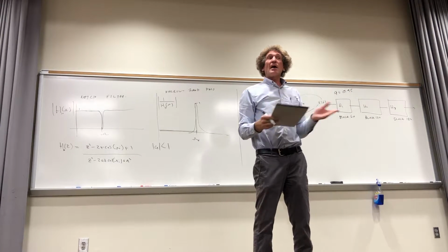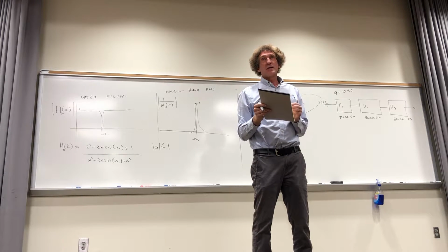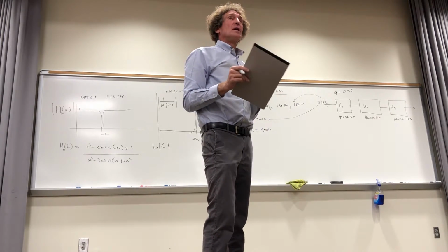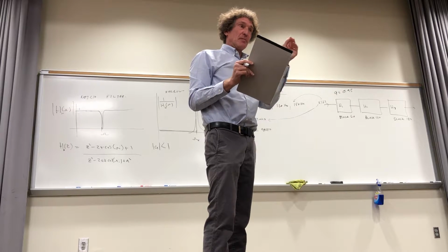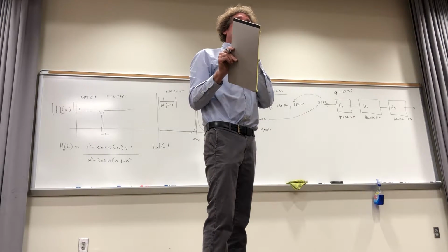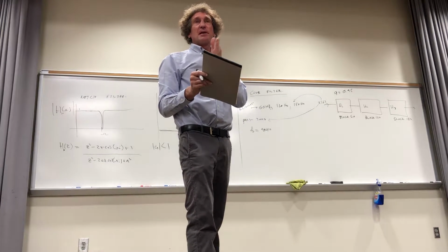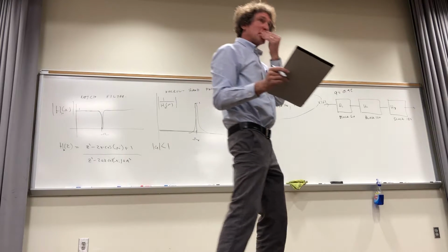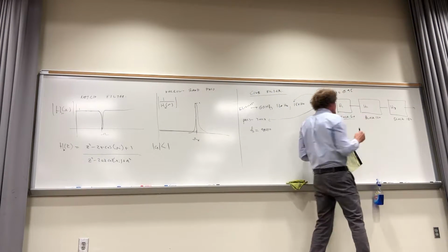Remember, the higher the value of A, the narrower the band is, right? But there are some problems because if it's too narrow and there's any jitter in the signal that you actually want to filter, you'll miss it, if you follow me on that. Remember, we always assume the ideal. We assume it's always going to be at that frequency, and there's no wobble to the frequency. Well, that's a falsehood. There always is.